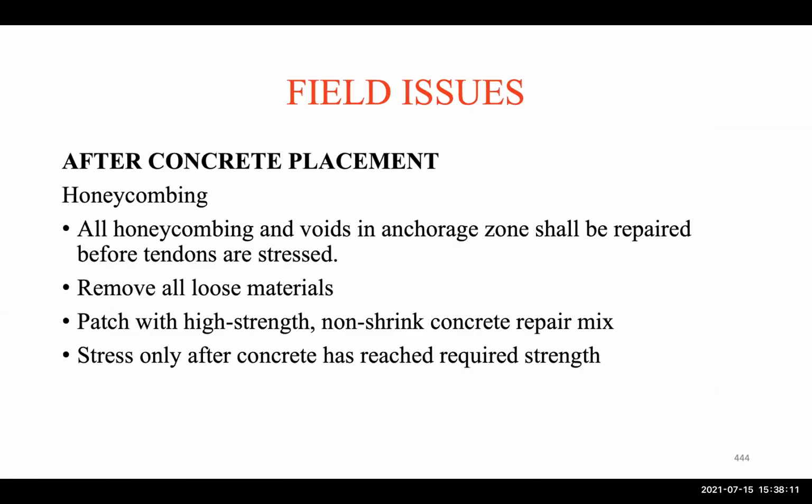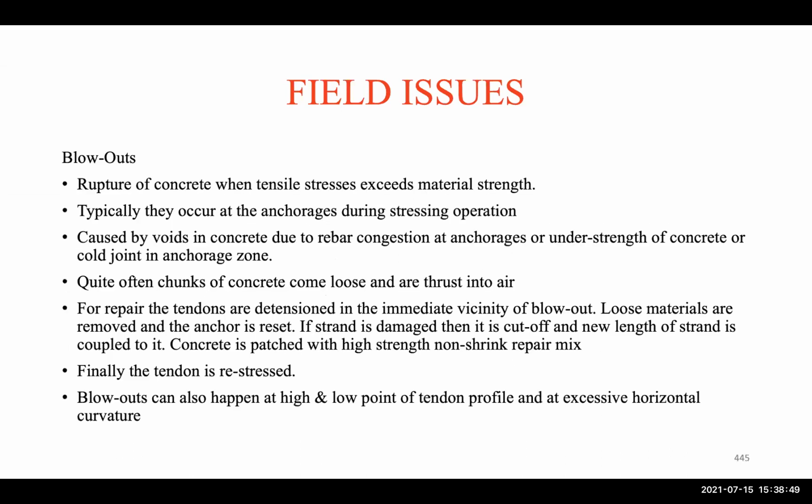And then after the concrete placement, okay, honeycombing. This is normal in concrete, so we have to look for that before the tendons are stressed. Remove all loose material, patch with high strength, non-shrink concrete repair mix. Stress only after concrete has reached the required strength. So if there are areas of concrete missing, honeycombing in the concrete, then we have to patch that with high strength concrete mix, wait until it achieves its strength, and then apply the pre-stressing.